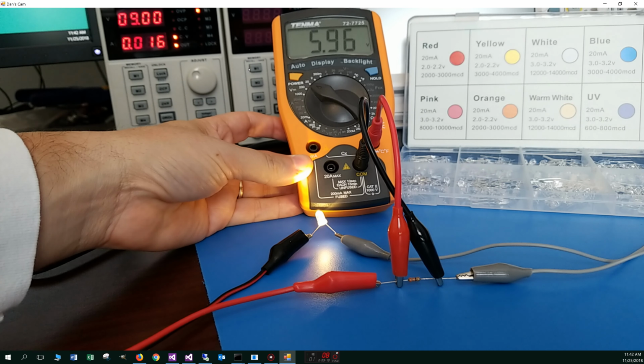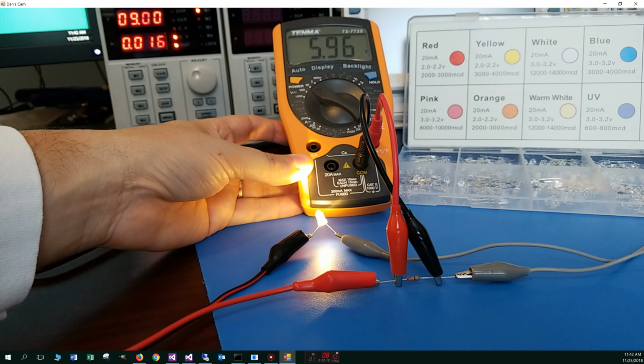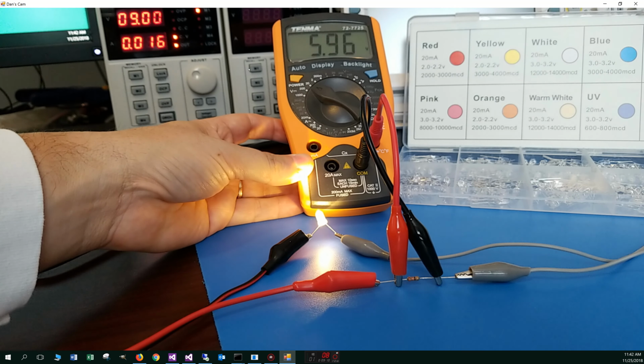And this is what's called a voltage drop across the resistor. So the resistor is kind of like, you know how I said it was eating voltage, right? It is sort of. It's consuming like 6 volts of electricity, so that the remaining 3 volts is exactly what we're sending through the LED there.